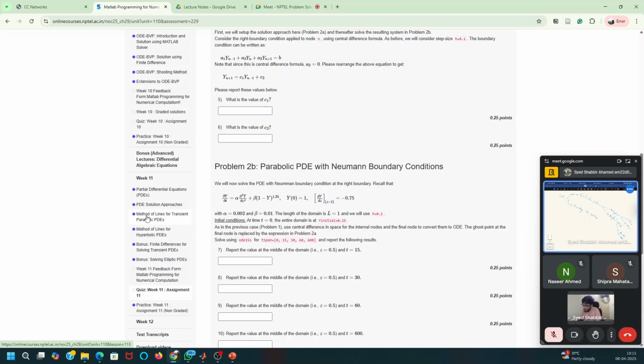In implicit methods, the problem can be solved without depending on the step size. No matter how big a step size you take, it will be solved. But the computations will be large, since sometimes there will be nonlinear equations which we have to solve. So it is a computationally expensive technique.